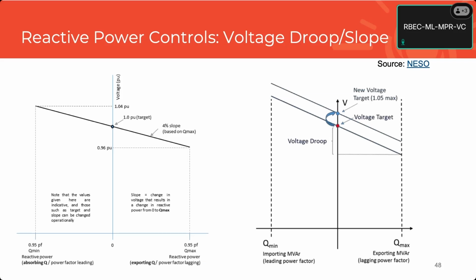So you can have two controllers that have very different response times. One of them comes in really fast and the other comes in really slow, and they'll push each other around on these droop slopes. So if you're not careful, you still can make them fight, but most of the time a droop, at the end of the day, once everything settles out, will define what the output is so that they're not allowed to be on hunting points in steady state.